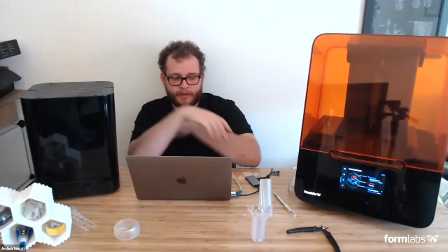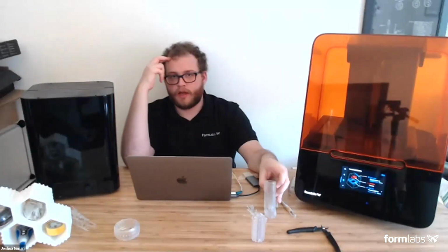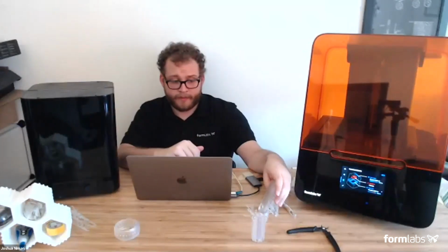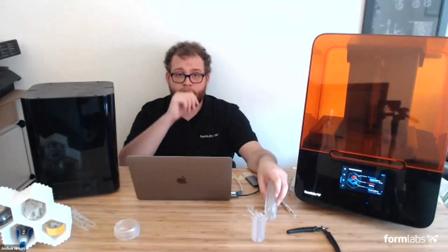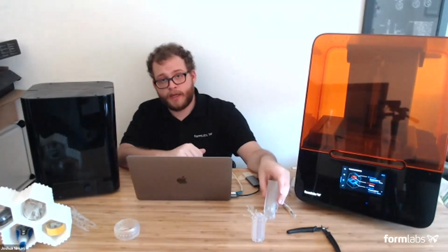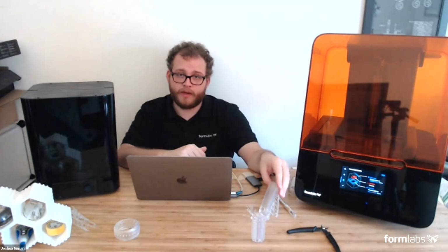So, a common thing for people to do is take something like this, throw it in the freezer, take it out, then hit it with sandpaper while it's still a lot firmer. But you can sand Flexible. You can sand Flexible V2. It's a little trickier with Elastic unless you've got it really frozen just because it's so soft, as you'd expect. But sanding is absolutely a recommended, reasonable part of the workflow.